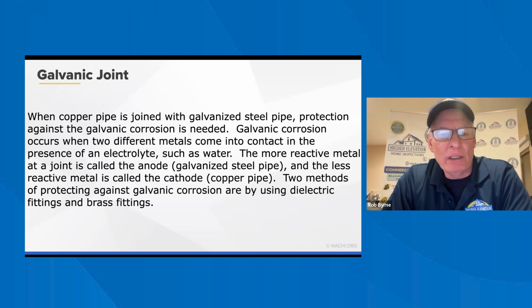What I always tell my clients is when you see the handle on the valve, if the handle is in line with the pipe, that means it's in the proper position, it's flowing. When you turn that valve a quarter of a turn, it's perpendicular to the pipe, it's off. Like in this case, it's covered, you really can't tell. But on the handle, a lot of times they'll have on and off in a direction you have to turn it. So this is a good illustration of a ball valve.